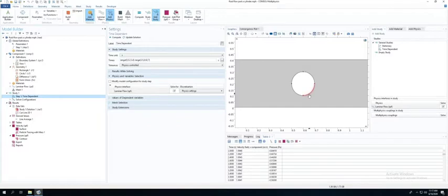Then I'm going to change maybe the diameter of this stationary object, make it larger, make it smaller, to see if I can manipulate the size of this object, and then reposition my velocity cut line again so that it makes sense. And then run this simulation again, and get that same velocity at 3 seconds again.